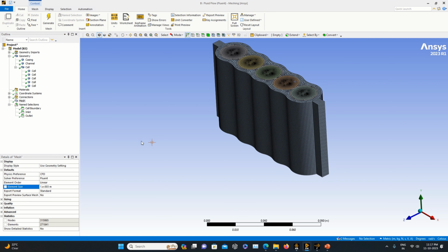Okay, so we already ran this, so I will just show you what kind of models and other things have been used. We have used the energy model over here. We have turned the energy equation on because definitely we are dealing with temperature, so that's why the energy equation is turned on. Then viscous, standard k-epsilon we have selected, with enhanced wall treatment, thermal effect and curvature correction. These options will be available only when the k-epsilon model has been selected, so that's why this has been selected.